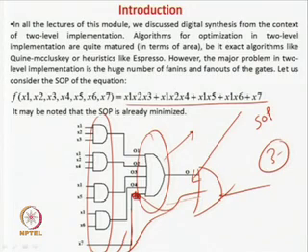But in this lecture we will try to do it in a much more standard way, so that the factorization, that is, the multiple-level implementation, is also in a very much minimized fashion. That means, again, the number of product terms or the number of cubes will be minimum, as well as the number of literals will also be minimum. So, that is how you have to do it.